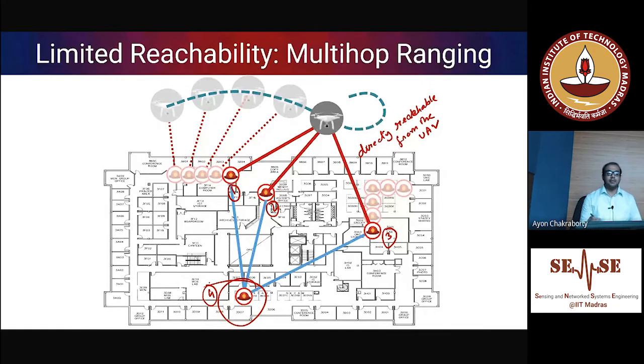Okay, and you have to modify the TWR ranging algorithm, right? It is not just going to be a simple TWR. TWR can give you the range of the individual links, right? It can give you this R_i, but how to orchestrate this entire system as a whole is an interesting problem. And if you are really interested, you can look up the paper. It's all online, so you can look up the paper and see what we have done.